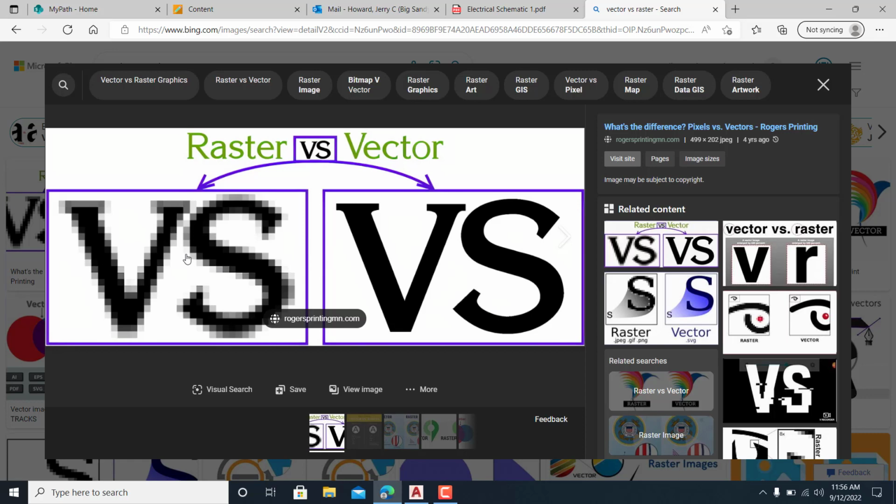If I zoom back on that, it would look really good, but the closer I get, you can see how it's pixelated. It's a little bit harder to get converted into a drawing as opposed to a vector file, and it will take an extra tool inside of AutoCAD to do that, the raster tools that you can get and add into your AutoCAD file.